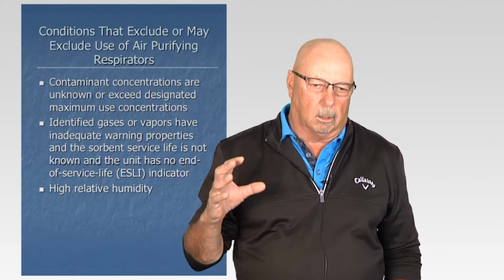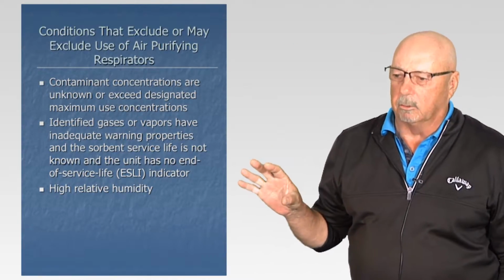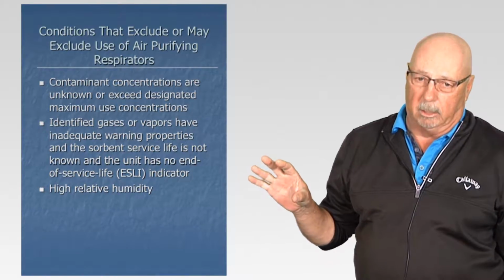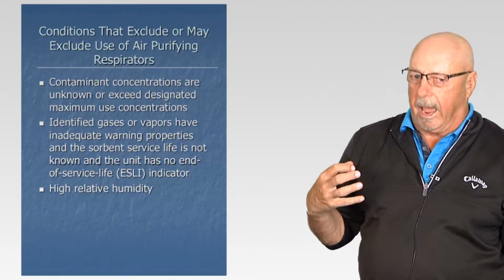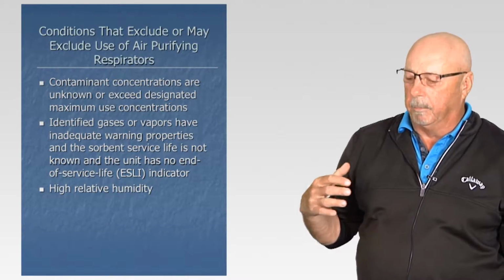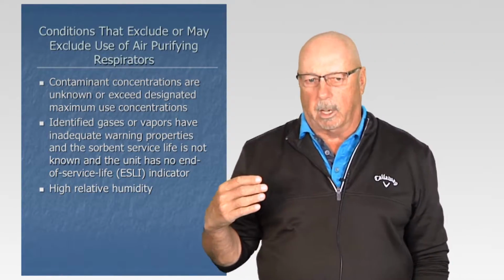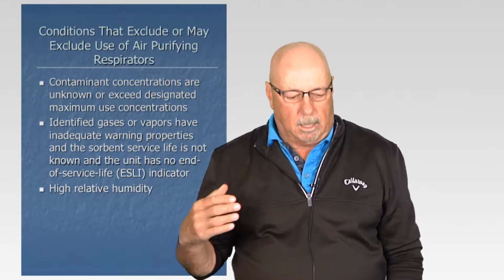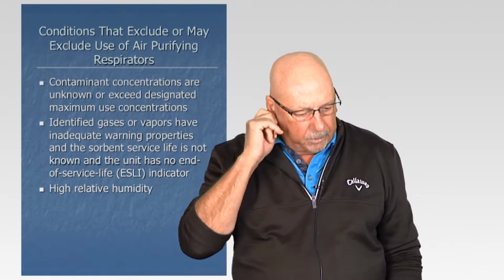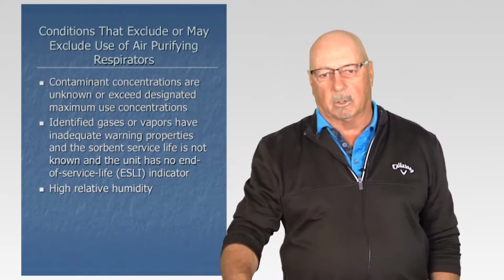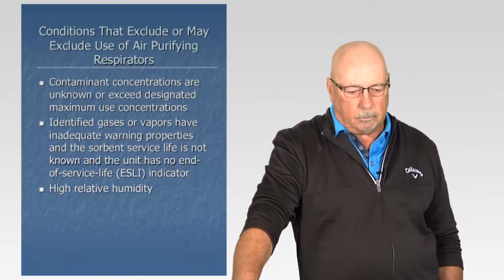So we need to look at what our concentration is in the environment that we're going to put the workers in, and what the protection factors of the respirator are, and make sure that the respirator protection factor is adequate to make sure we don't exceed the maximum use concentration for that respirator.